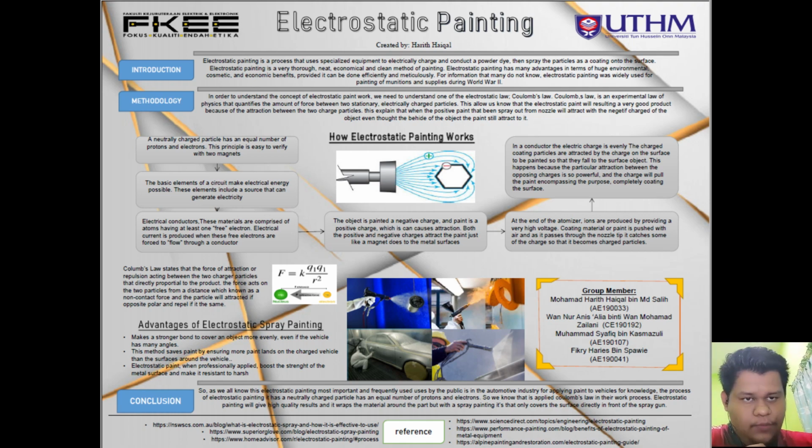When the paint is applied, it needs to keep a constant distance, because when it sprays too far or too close, it will not cover all the surface, especially behind the object or at a difficult angle of the object. This is because when the positively charged paint is shot out from the nozzle, it will cover all the negative charge of the object, including behind the object or the difficult angles that are hard to reach.